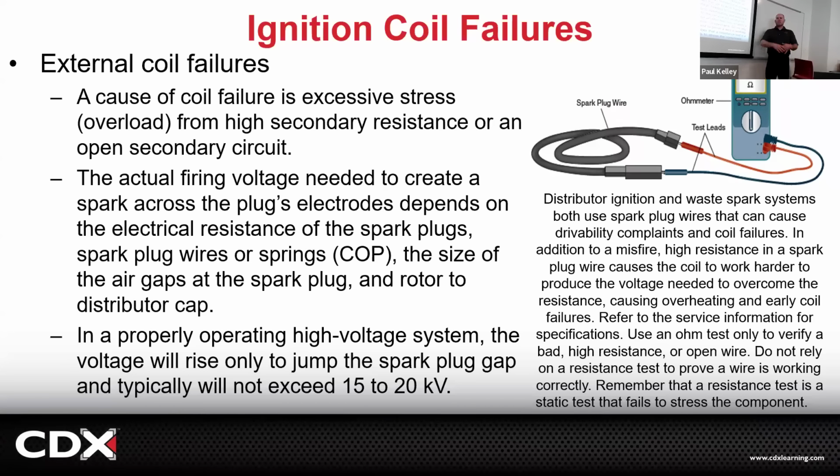Now you kind of see why we would do tune-ups as like a whole cap, rotor, wires and plugs. We'd throw a bunch of stuff in it and it'd be good for a while. And we'd throw a bunch more stuff in it, it'd be good for a while. It wasn't real common that we do a coil and not the cap, the rotor, the wires, the plugs, because secondary ignition resistance would be potentially the cause of why the coil failed prematurely. Now coils do fail over time anyway, I acknowledge.